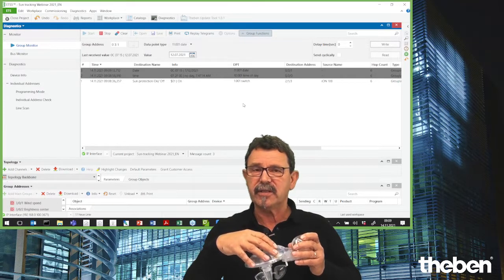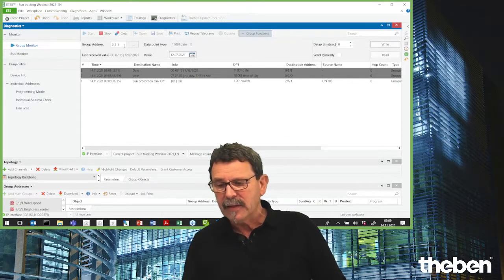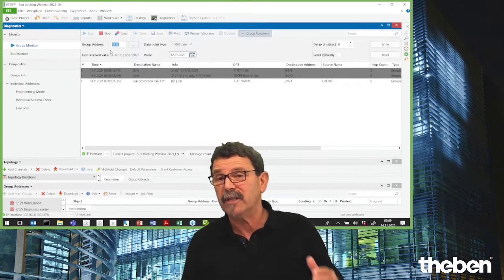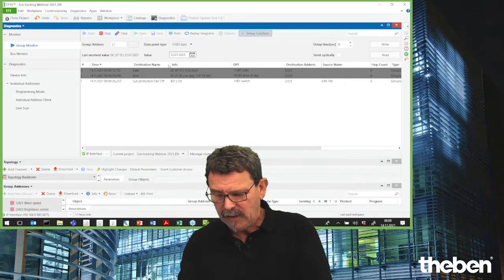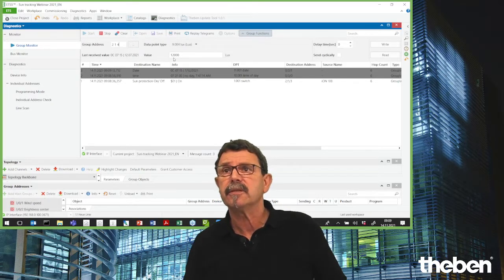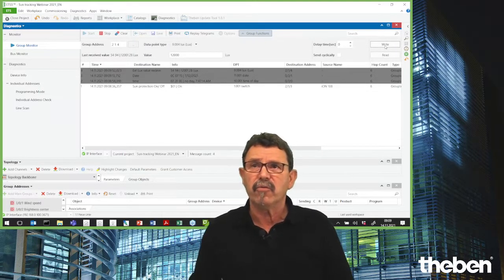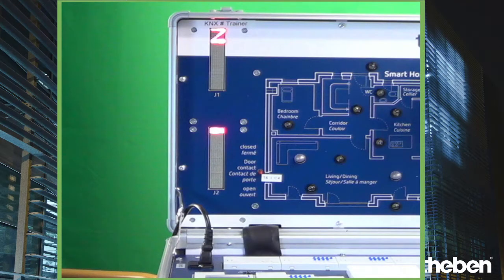We do have the current daytime of 7:45. So, and then we need, okay, to have some brightness value. So brightness value, currently we are definitively underneath the preset value. And for that purpose, I need to send a value. So 12,000 lux, just as an example. And for that purpose, okay, I write this now, and the panel is moving down now the blinds to the reasonable preset position. Okay?